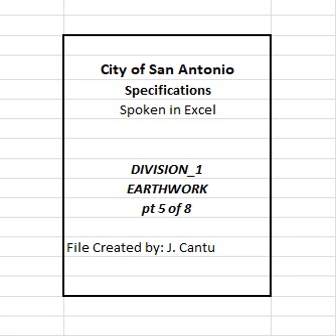2. Density control. Compact each layer to the required density using equipment complying with Item 210, Rolling. Determine the maximum lift thickness based on the ability of the compacting operation and equipment to meet the required density. Do not exceed a layer thickness of 12 inches loose material, unless otherwise approved. Maintain a level layer to ensure uniform compaction.